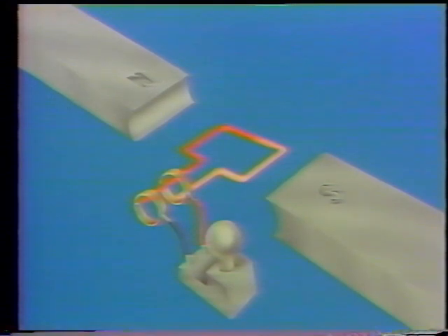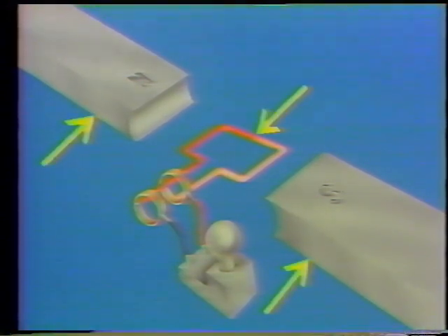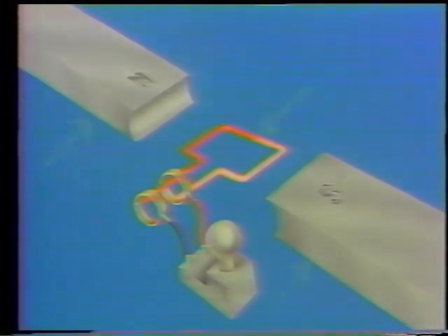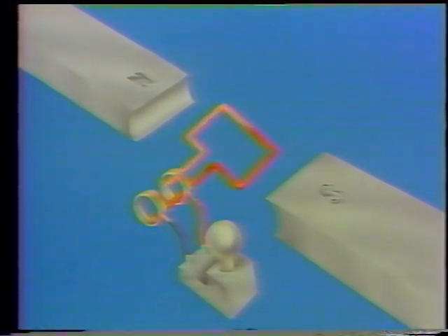The second convention is the use of degrees. Most AC power sources have a moving part. As you know from our discussion of magnetism, we can get a current if we induce a voltage. To induce a voltage, we need a magnet, a conductor, and relative motion. In many cases, like the model you see here, the moving part rotates, that is, it goes around in a circle. A circle contains 360 degrees. The convention, then, is to use degrees to indicate where the moving part of the AC power source is in its rotation.